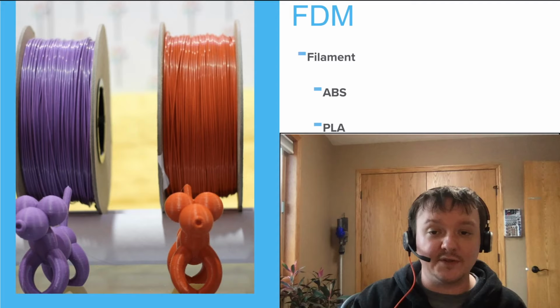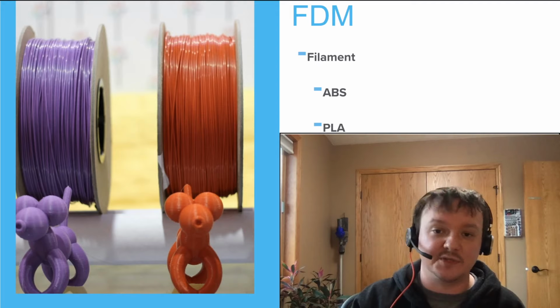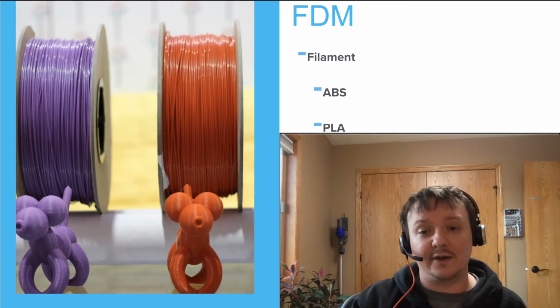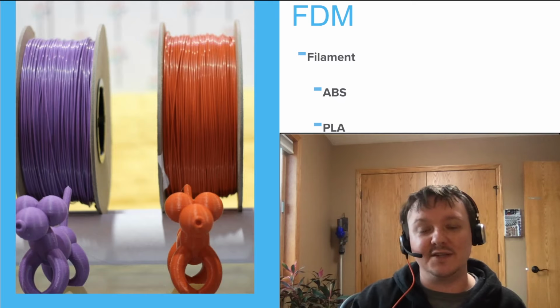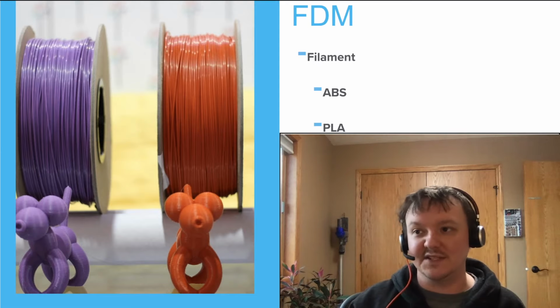A lot harder to print than the others, but you get flexible materials, which can let you do some really interesting things. The other thing I should mention is not all filaments are created equal, especially with ABS. ABS definitely smells way more than the other filaments, and there are a few people who warn about the fumes themselves. It's best not to sniff melting ABS for extended periods of time. If you want to use ABS, you generally need some sort of an enclosure just to enclose all of those fumes, just for safety's sake.